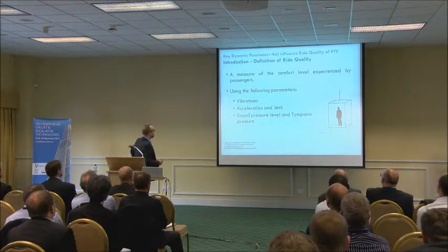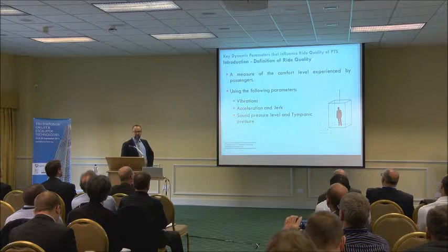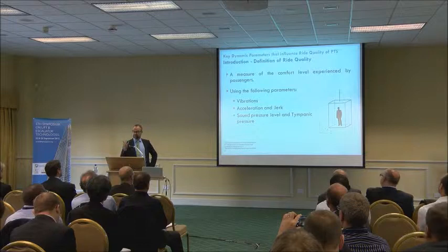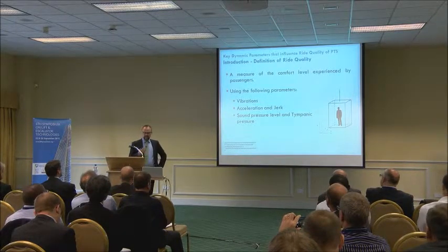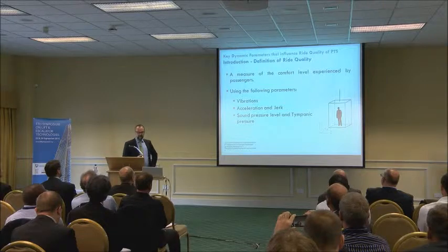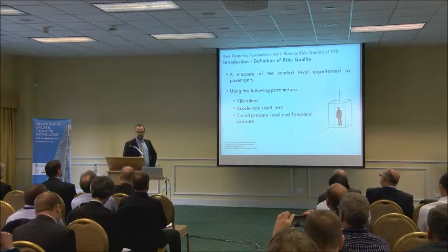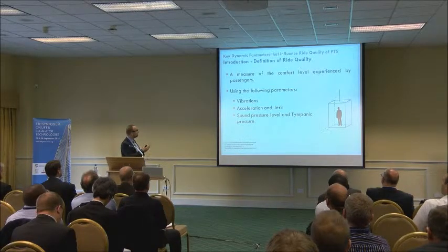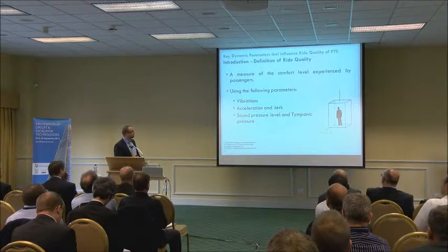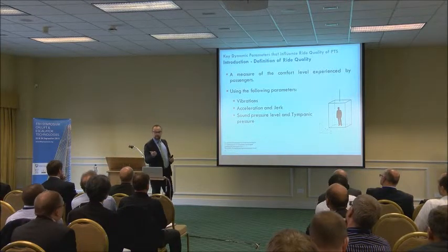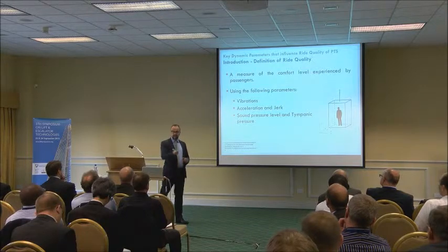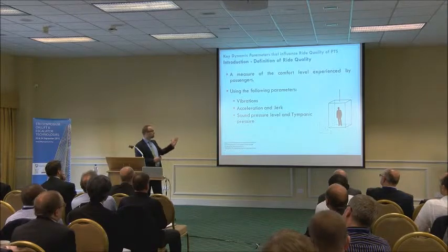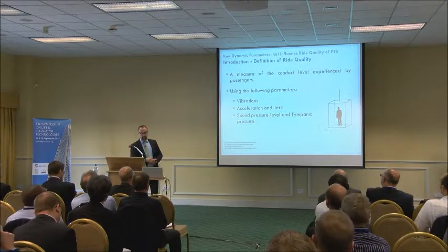Let's define ride quality. What is ride quality? Ride quality is a measure of the comfort level experienced by the passengers, and again, that's subjective. It is intimately associated with the subjective perception and sensitivity of motion and to sound of a moving lift car in this case. It uses the following parameters: vibration, and in vibrations we talk about three directions, X, Y, and the Z direction, acceleration and jerk, and sound pressure level and tympanic pressure.